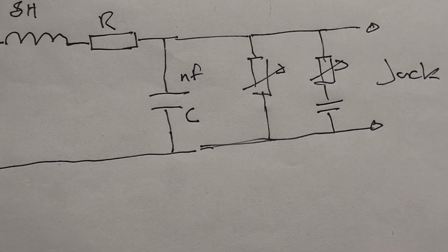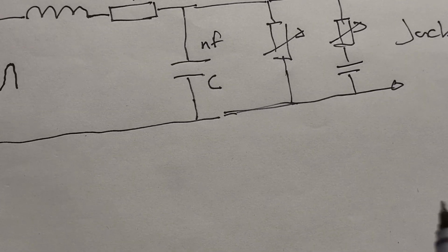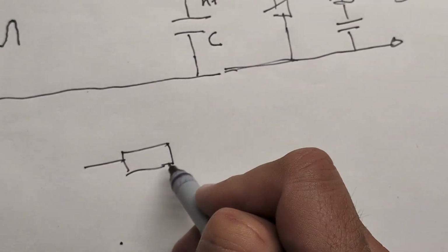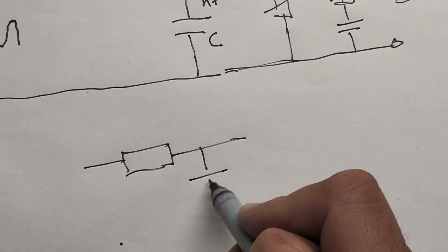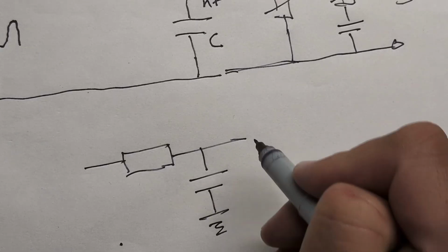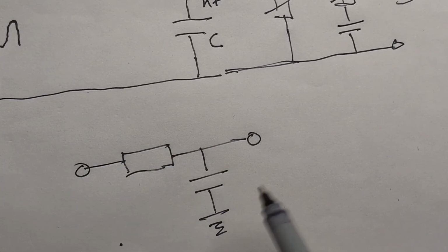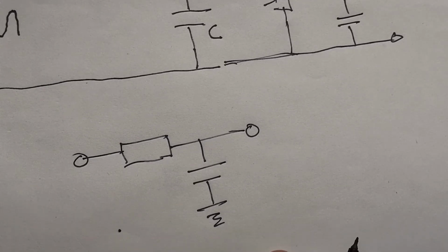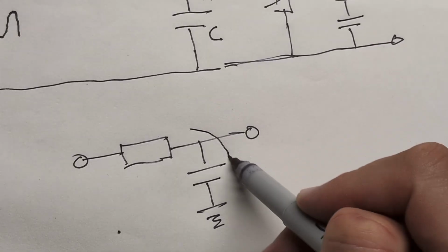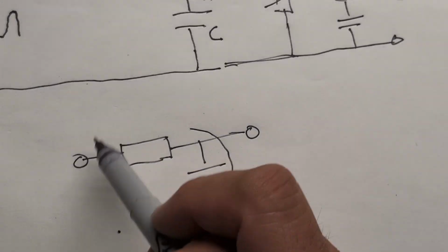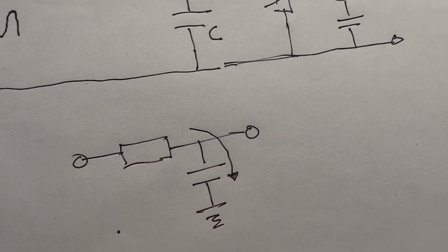But it connects to the fuzz face actually through a cable, and the cable electrically is similar. It has a resistance and it has a capacitance. And the longer the cable is, the bigger this capacitance is. So the longer the cable becomes, the less higher frequencies will pass through the cable, and they will be passed more down to ground and attenuated. And that's one of the reasons why we use a buffer, is to eliminate the effect of the long cable and produce a much brighter tone.